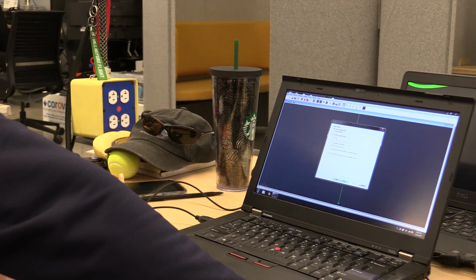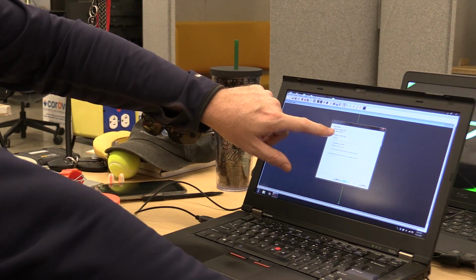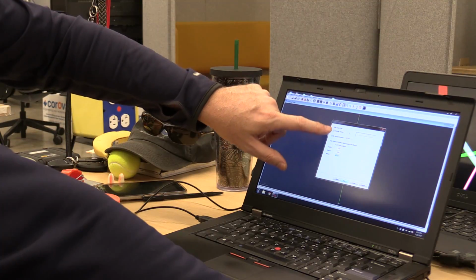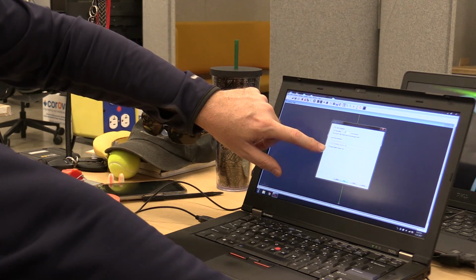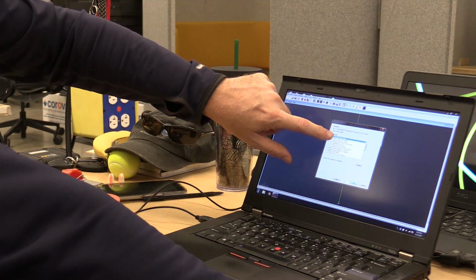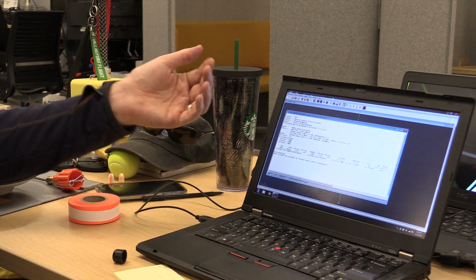It says ensure the process datum is WGS-84. So next window, datum WGS84. That's correct. And then the next window, I do nothing. I make no changes. Next window, I make no changes. Next window, it tells me the GPS date, month, day, year is going to be provided. Then I finish, and then this is the end.